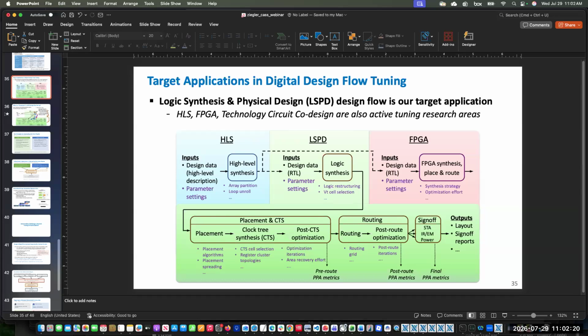So I think from an embedded systems background, you probably have a lot of the front end, which is fairly common. Let's say the RTL and the simulation: you can take a piece of RTL and send it through FPGA or ASIC flows almost identically. So that part you probably have. Where it diverges is what you do to implement or realize the RTL on hardware.